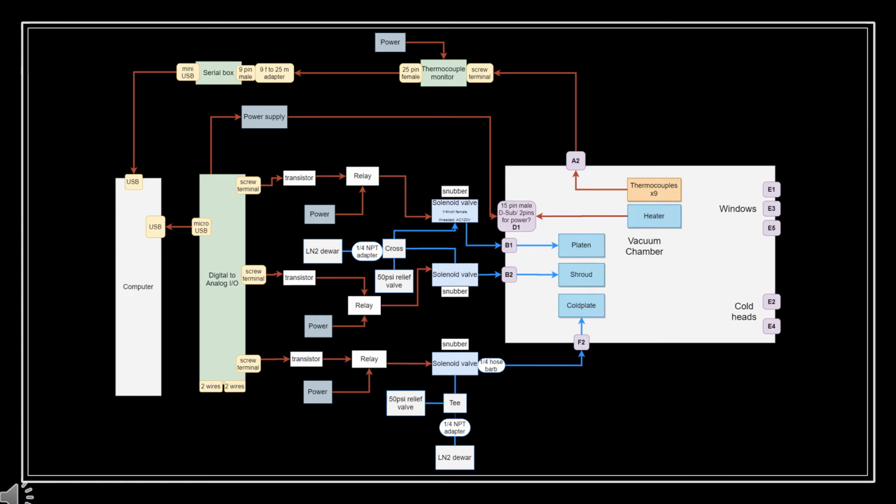The deposition plate has also been upgraded to include an electronic heater. This heater allows for finer control and minimizes the unpredictable effects of hysteresis that liquid nitrogen often suffers from. Thermal control has also been automated. By taking readings from the thermocouples placed strategically around the chamber, the heater and liquid nitrogen flow are adjusted automatically to meet user-specified temperatures within 1 Kelvin.